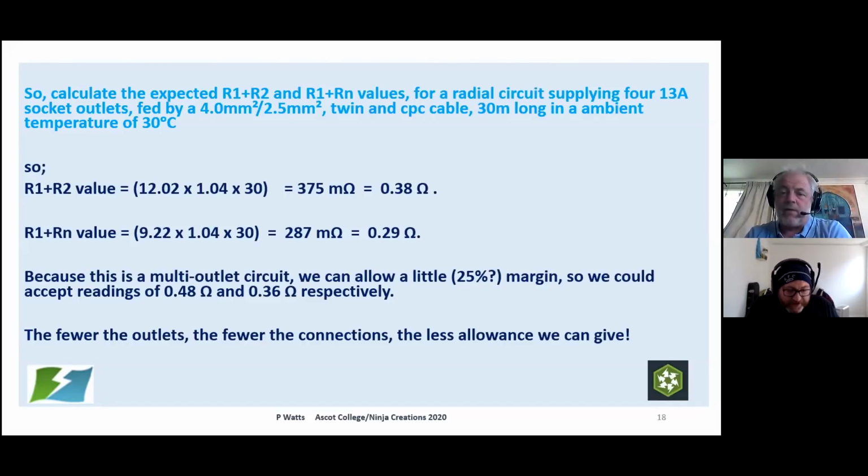You can switch that switch over multiple times and it will change the reading all the time. But that's the thing with the low resistance ohm meter, and that's why it's great with those courses, because you can get the guys to really understand how much movement there can be in the values with a simple twist of the socket, or a couple of insertions just to attack any dirt in there.